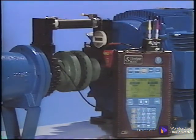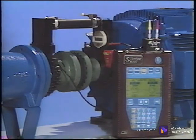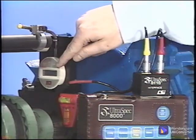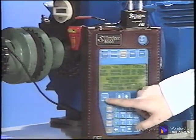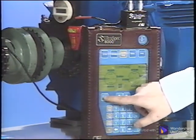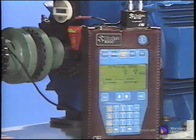The reverse dial indicator method can be simplified with electronics, such as this CSI Model 8110, which uses a patented method to automatically compensate for bar or bracket sag. The principal difference between the reverse dial indicator method and the electromechanical system is the dials are replaced with digital heads that make the readings and transfer the data into an alignment analyzer, which calculates the machine moves and required shims under each foot. Although the electromechanical system is more costly, the calculated moves reduce time and minimize the error factor, saving manpower and downtime dollars.